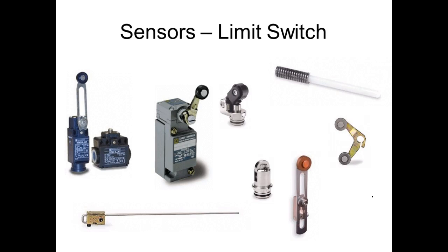Because the slower they break, the odds are the longer they're going to create an arc, and when they create an arc, it creates ozone. Ozone has low resistance. So normally if an arc is created, it's hard to get rid of, especially DC. AC helps to extinguish it because AC drops to zero. Alabama Power transmits 60 AC cycles per second, so that means it drops to zero 120 times a second. So AC has a tendency to self-extinguish. It don't mean it is, but you got enough push, right? But with DC, once you get an arc, it's hard to extinguish. So we have to use techniques.